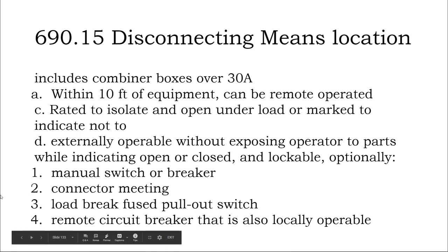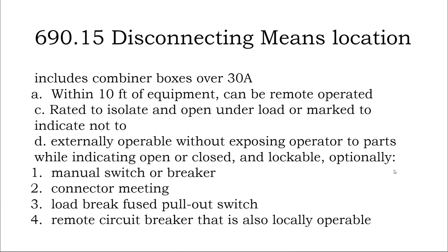But it says it can be a load break fused pull-out switch, like an air conditioner disconnect, and be compliant as the solar disconnect. Most local jurisdictions step in and say, no, we want you to use a knife switch.